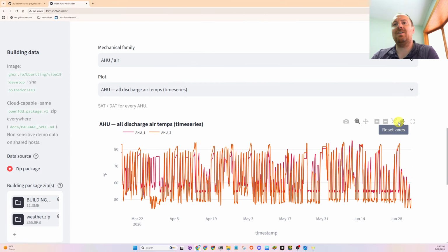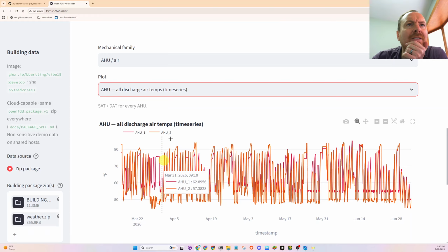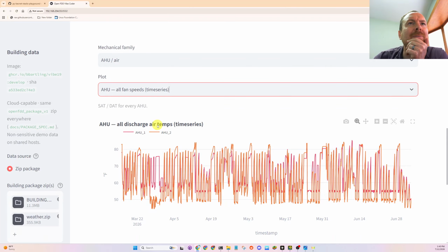So if I would write a write-up, I think the outside air temperature sensors are off, and if it's a Niagara system, we can get free weather data from the web and reduce mechanical cooling runtime. And some of these resets seem really off. There might be a couple of VAV boxes that are flaky, a couple of flaky sensors out there. And I am missing the box plot for, oh wait, maybe it's coming here.